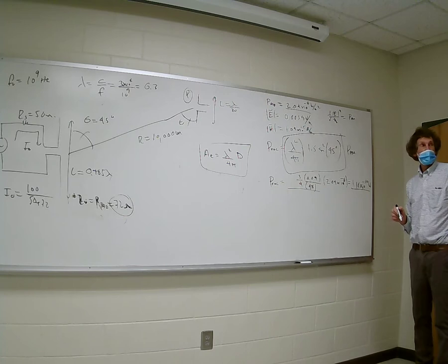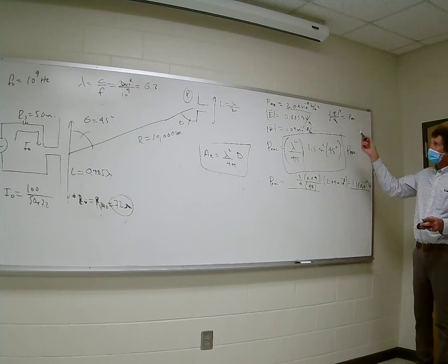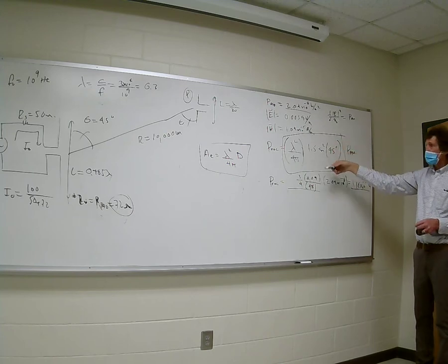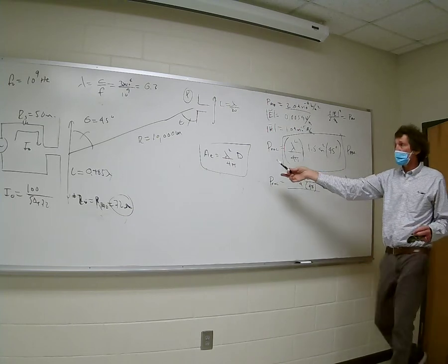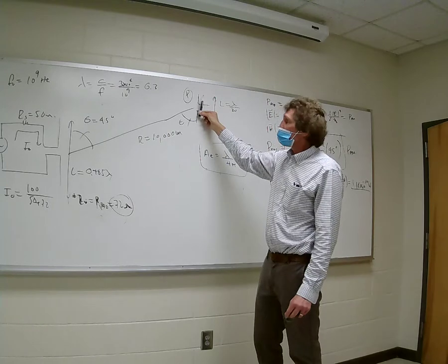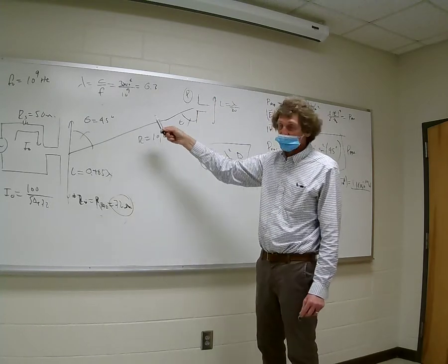Yeah, that's it. All right, now that's nuance, but the progression is always average power density, right on target, and then it's multiplied by the area, and the area is lambda squared over 4 pi times the directivity, right? Now here's the thing, I had this aligned so that this angle and that angle are the same. The directivity is different because it's a short dipole.